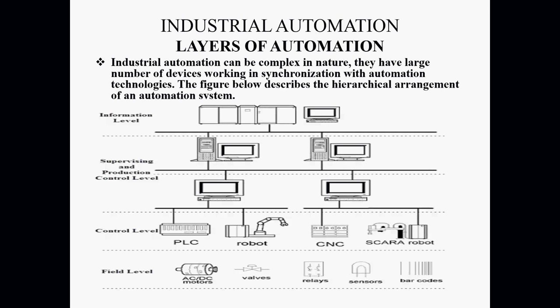So I start at the field level with the field devices like pressure sensor, temperature, and motor. I go to the control level with the PLC, and the supervisor level with the SCADA in the control center. It means that the PLC is most of the time at the remote terminal unit, outside on the field. But when you get the information, you send it to the SCADA in the control center.